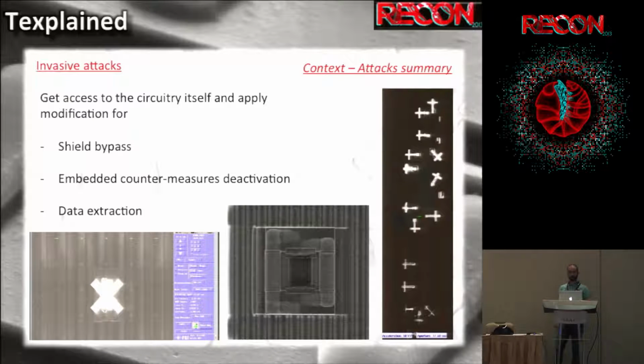On the second picture, I wanted to have some space to reach something that was below, so I had to cut the 2 lines and replace them on the side, and the chip will still work. And in the last picture, all these crosses are probe points, so there are 16 pads to put needles on a bus and get the data.